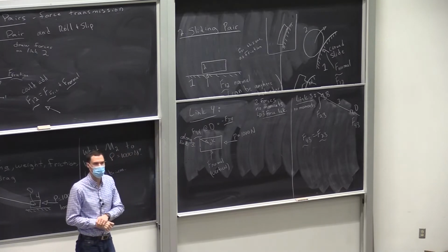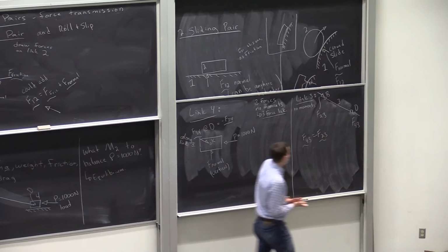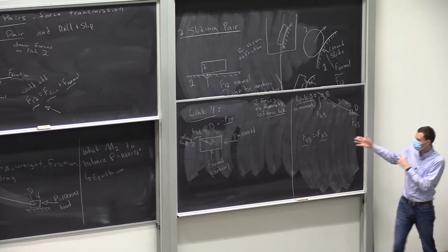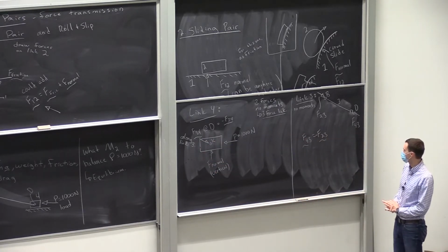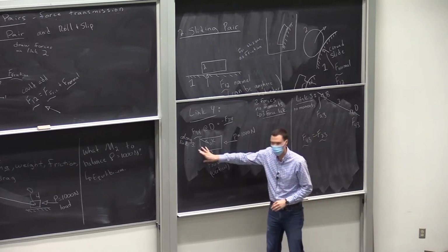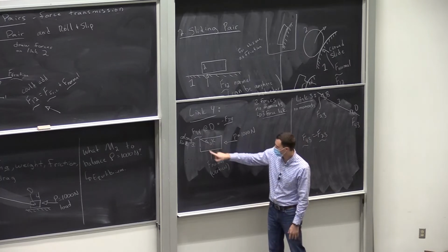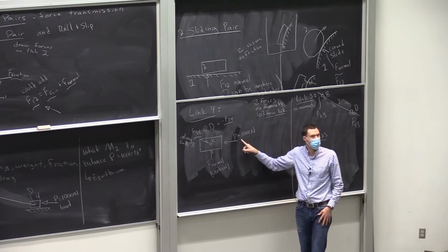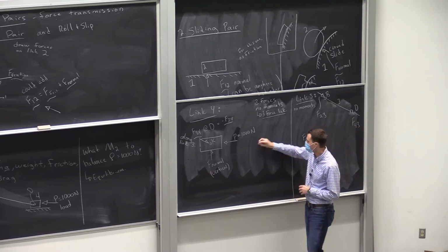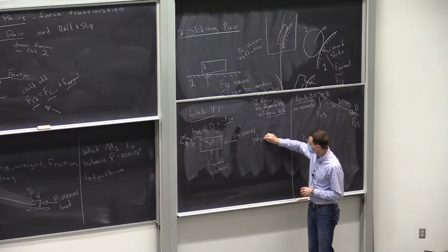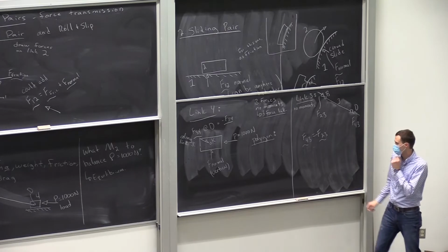Any questions about that one? That's a key step for our problem. Great, but we still haven't calculated the magnitude. So let's go back to our link 4 and say, do we have enough information now to do it? We have directions of all of them, and we have the magnitude of 1. And if you think back to last lecture, that's 3 force links. That's enough information to solve our force polygon. So as soon as we have a few directions and a magnitude, we have enough to solve it.